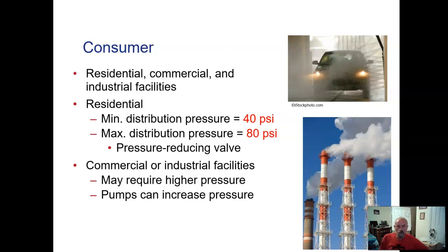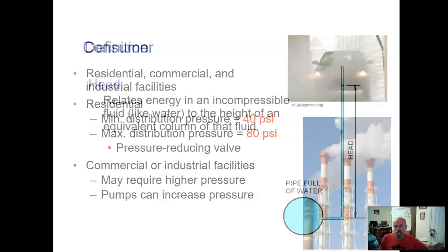If you've ever turned the water on and shut it off and you hear a big whack, that's the water pressure coming to a stop in the pipes. And building codes often require pressure reducing valves at the service meter when the distribution pressure exceeds 80 psi, like I said.